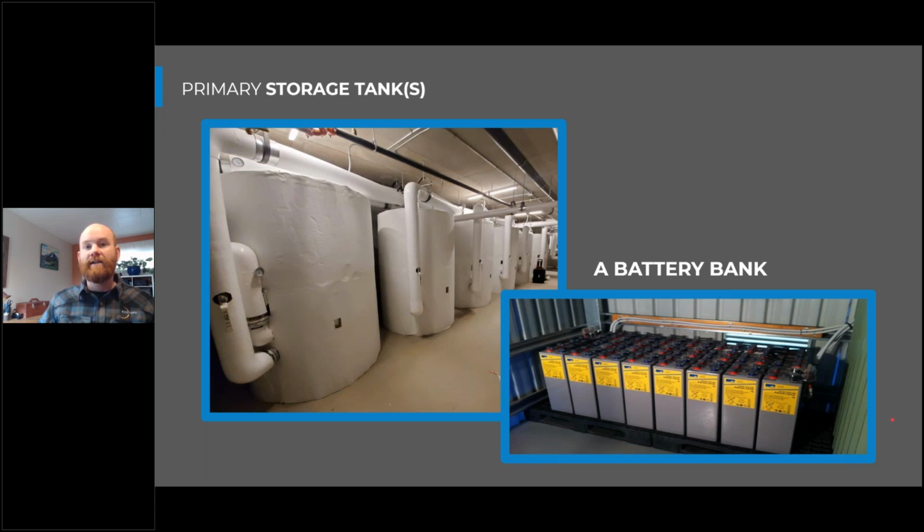And because the recovery rate of the heat pump water heater is typically more than traditional gas systems, we might want to prioritize more thermal storage to have a less expensive first cost for our system installation.